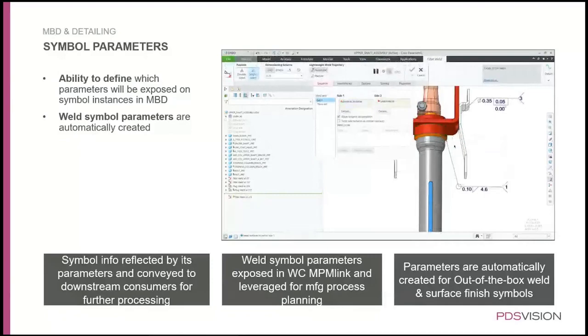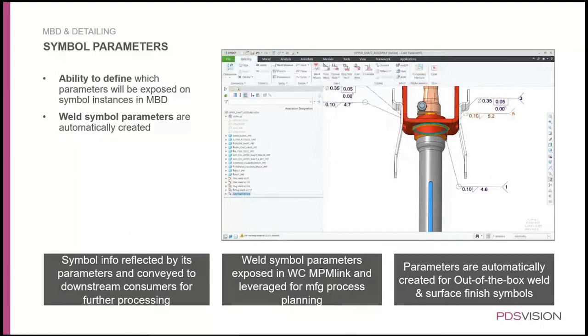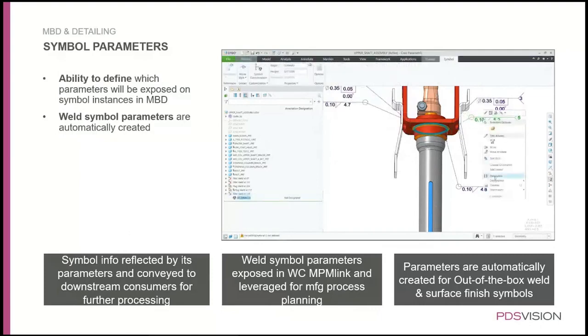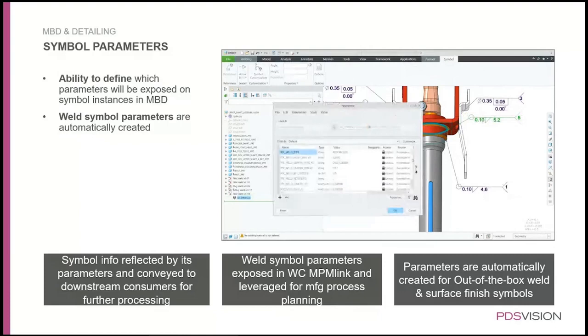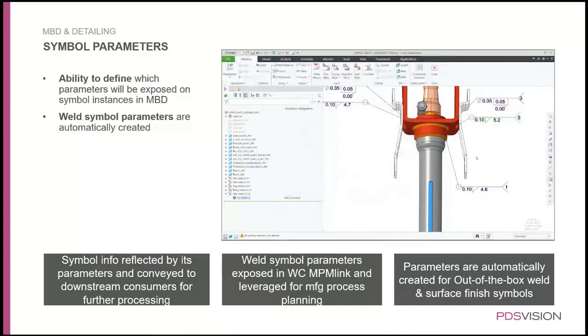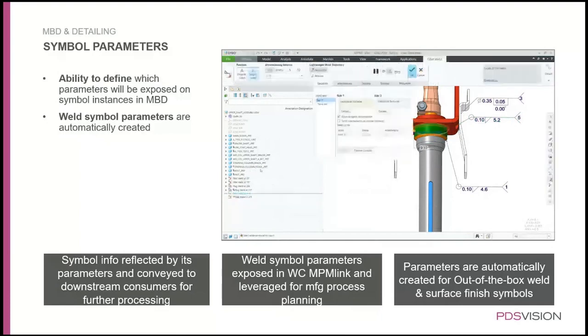So first we make a fillet weld in there. You get the surface representation of it. You put the A dimension 0.1 inches, I think. And then if you take a look at what are the parameters for that particular weld, you will find out that A size or fillet weld leg size is in there, 0.1 inches. And should you want to go and change that, of course, the parameter information for that weld will change as well.